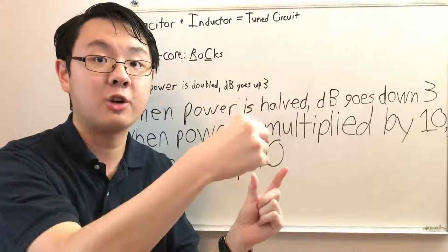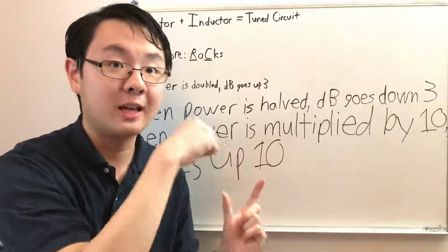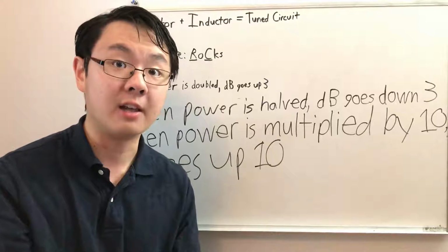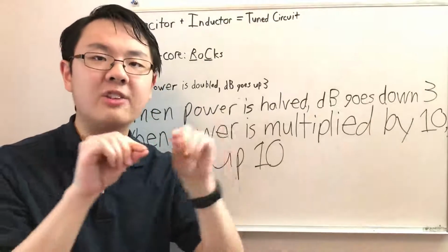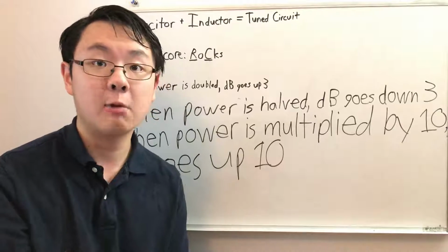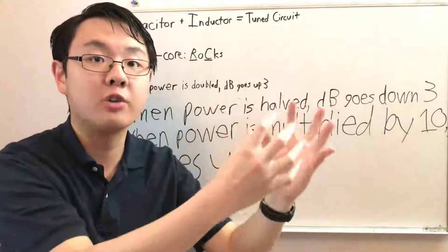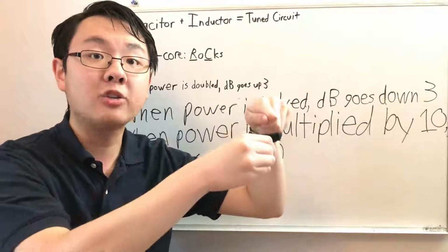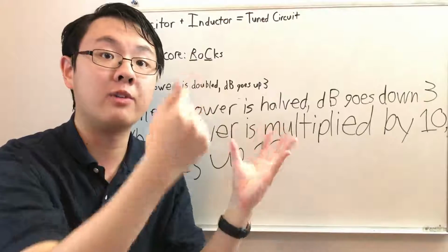So then we drop the capacitor, we put the wires through the holes, and then it's in the holes, but it's not really a tight fit. So the capacitor still isn't connected to the circuit. This is when we solder everything together. What we do is we melt some solder. Solder looks like a thin piece of metal wire. And we get what we call a soldering iron, which is very, very hot. When we touch the soldering iron to the solder, it melts and liquefies. With a soldering iron and solder, we can melt the solder around the hole and around the little wire sticking in the hole from the capacitor or resistor or whatever.